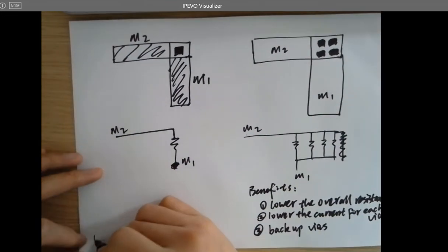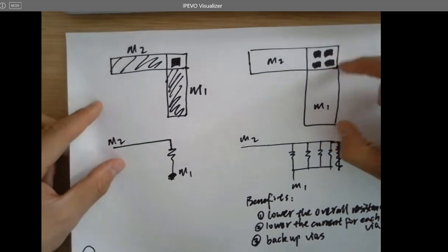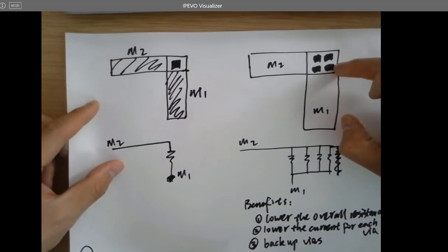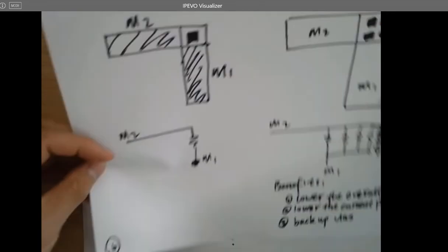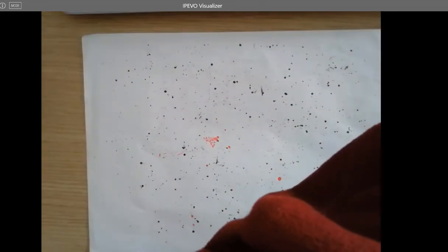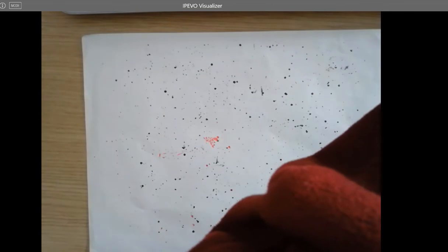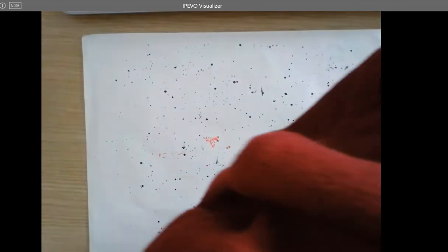So it's mandatory. Whenever you have a large area, you definitely will have a via array instead of one big via, which can definitely improve the yield for the chip. Yield, Y-I-E-L-D, is a critical parameter for IC fabrication.